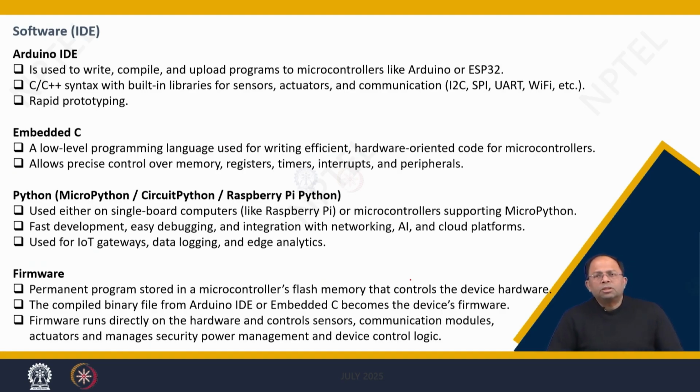So then coming to the software part or the IDE part, there are different IDEs depending on which microcontroller you use. You may have to use different IDEs. For example, if I use an Arduino board, then I will go for the Arduino IDE, and we use it to write, compile, and upload programs to microcontrollers.